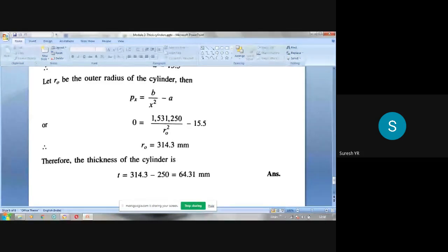That is sigma Fy = 0, and sigma M = 0. Sigma M = 0 means the algebraic sum of the moments of all the forces including reactions taken about any point should be equal to 0. So these three are called the equilibrium equations. Once a structure is in equilibrium, all these three conditions should be satisfied.